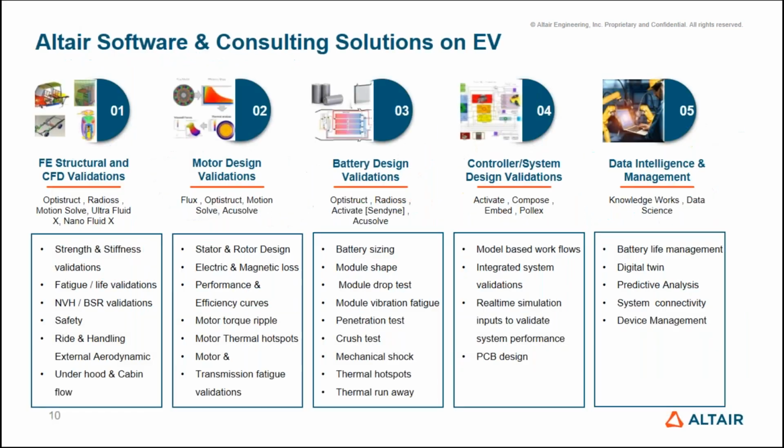Apart from that, from the electric vehicle perspective, right now everyone is talking about electric vehicles. The technology disciplines which we can cover through the Altair product portfolio start from the FE structural and CFD validation. You can see on the left hand side the solvers basically used, OptiStruct, Radioss, and the applications you can cover, like strength and stiffness validation, fatigue, NVH, ride and handling, external aerodynamics, underhood and cabin flow. That is all covered through FE structural and CFD validation.